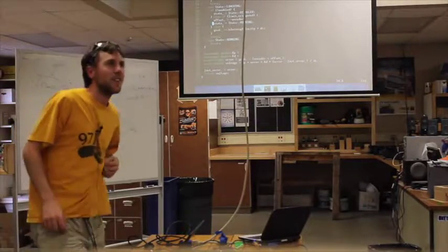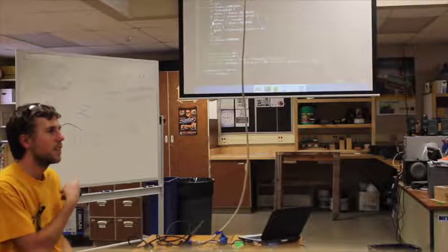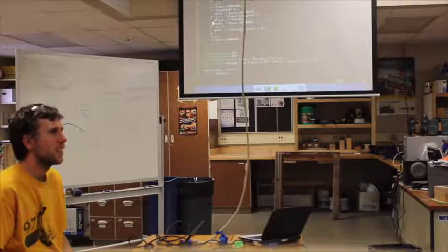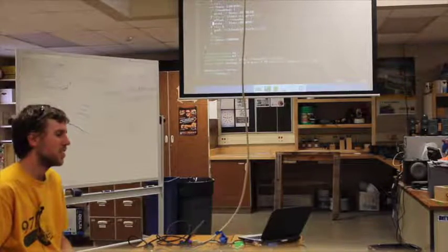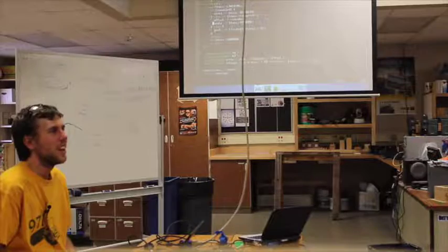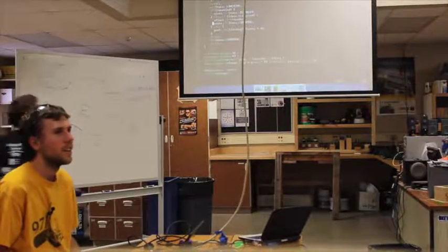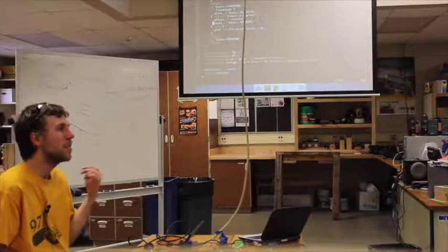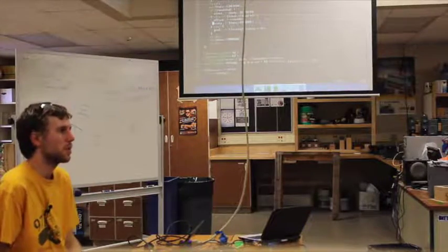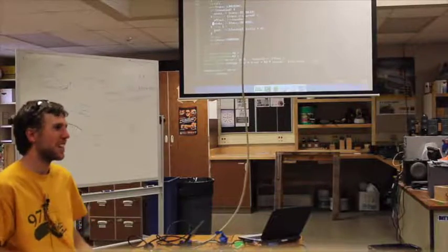Oh, okay. Can I ask a quick question about the Hall effect that you guys use? Yeah, I designed it. I know a lot of the ones we buy have an arbitrary limit on the flux that they return high. Do you know of any that actually allow you to configure that? The data sheets are not very precise. No, I mean ones where they give an analog output. Yes, you can buy those. The same chip family will have that. So all the ones we see that are analog are tiny little things? You can't buy a board for it? Me and some of the students on 971 designed the board sold by West Coast Products. Oh, okay, cool. So that's only commercially available because we got tired of making our own.